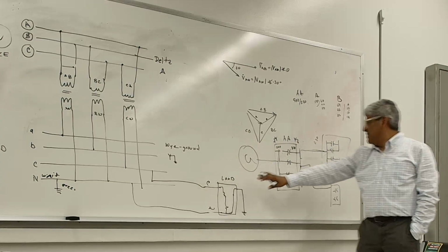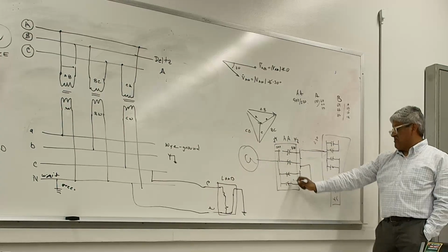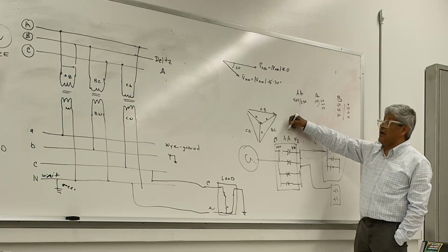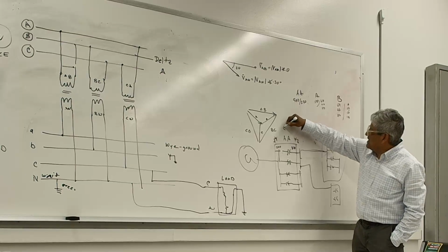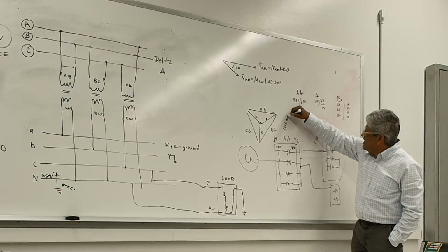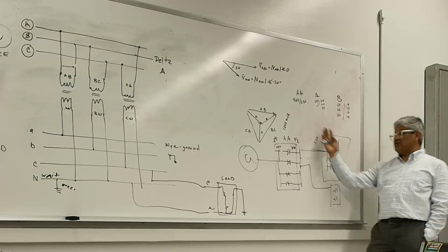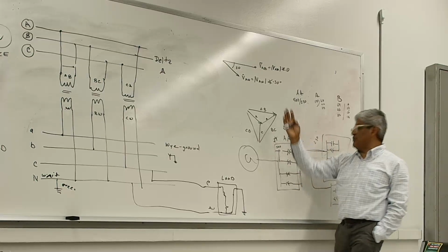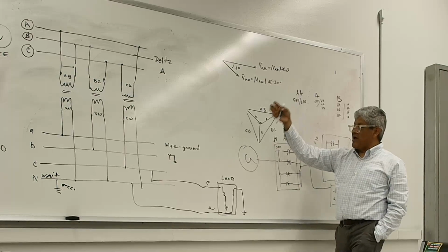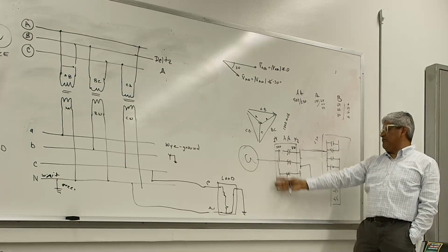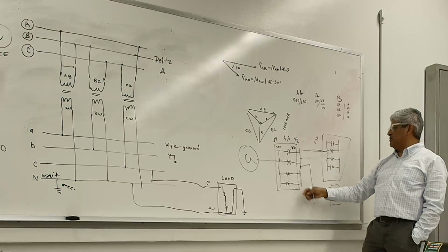Correct. Okay. Correct. So now from that substation, this substation has a capacity of, I'm going to take a number, 1,000 MVA, right? So far so good. So I have 1,000 MVA of transformation, and there's 3-phase transformers, wye grounded on the primary and secondary, meaning wye grounded on 500, wye grounded on secondary.